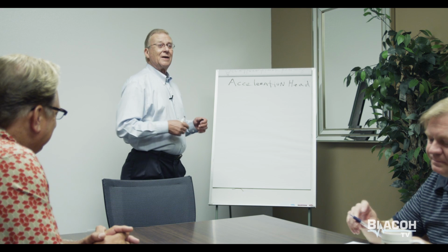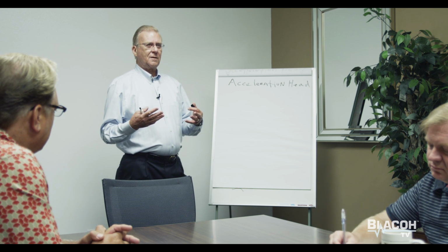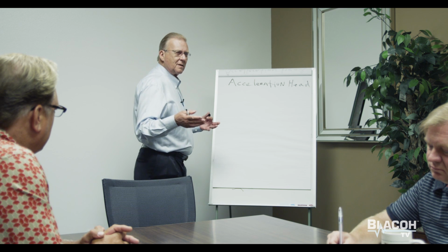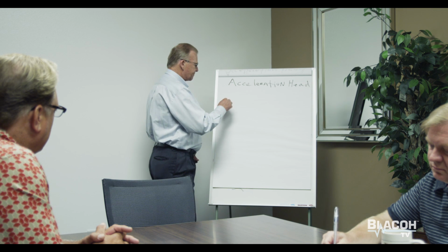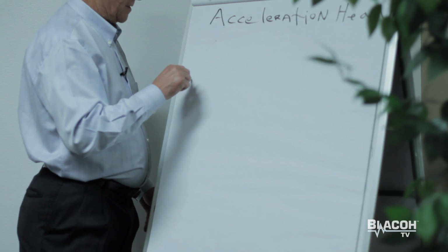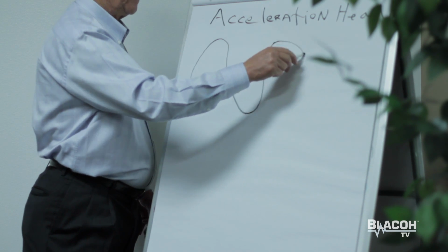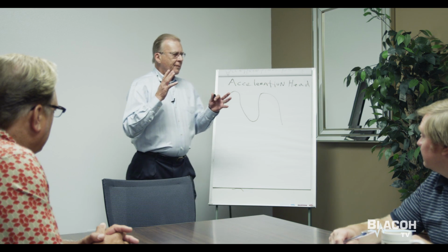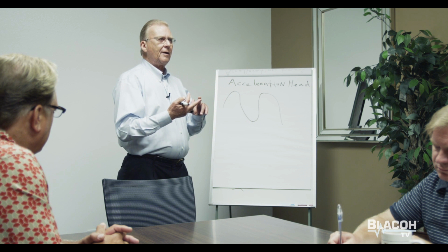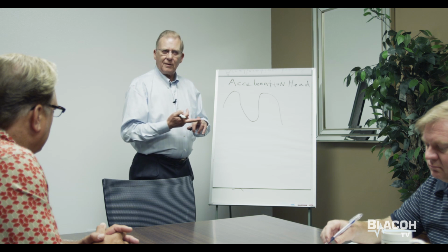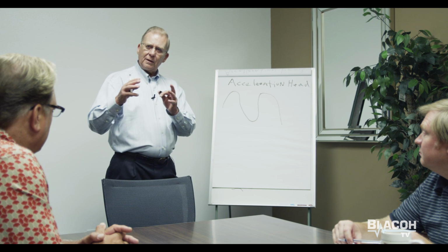So we're going to have a little discussion about acceleration head. Now, acceleration is the change in velocity. And we can see this in basically a pulsation curve, which is a sine curve, a modified sine curve, depending upon the type of pump used in piston, in diaphragm, even in the rotating peristaltic pump. A given amount of liquid is captured and then expelled.